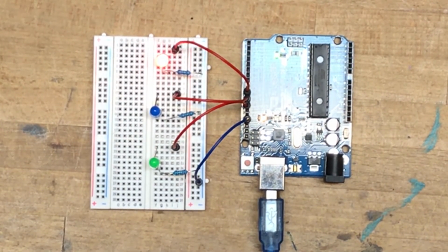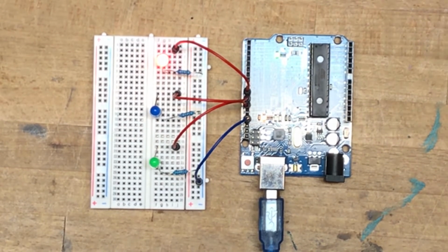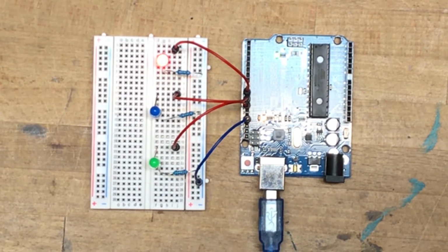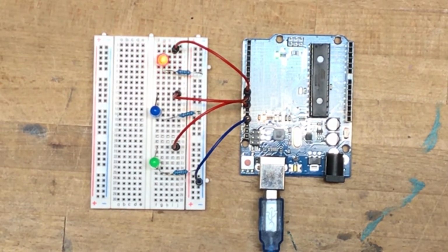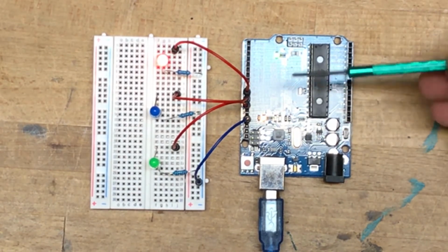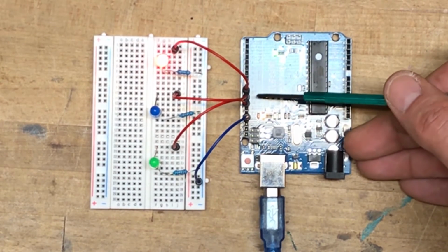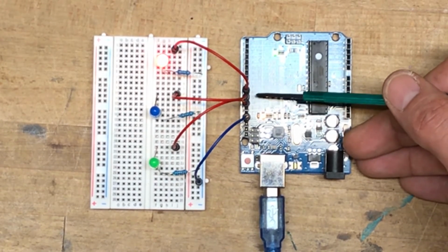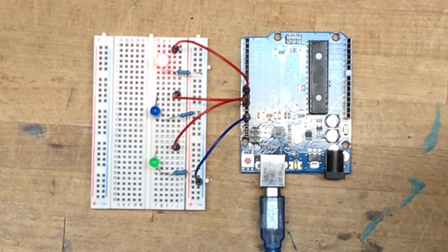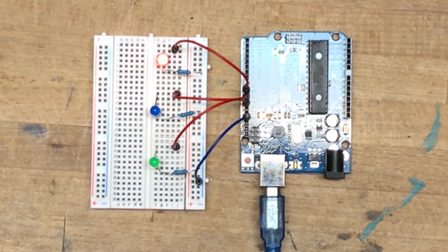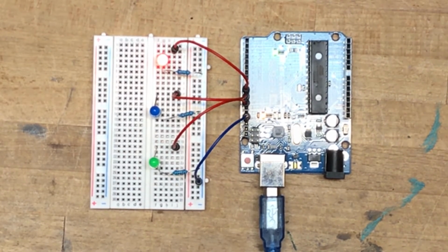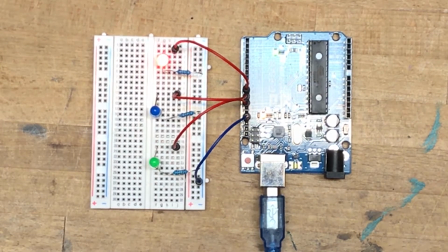We're going to be starting here with essentially the same circuit we ended on last week. Three LEDs, three 220 ohm resistors in series with each of those LEDs, going back to negative. The only difference is this week we have our supply high pins plugged into 9, 10, and 11. Those are digital pins 9, 10, and 11, and you'll see those numbers have a little squiggly mark next to them called a tilde. That indicates that those pins can approximate an analog output signal, and that's what we're going to be playing with right now.